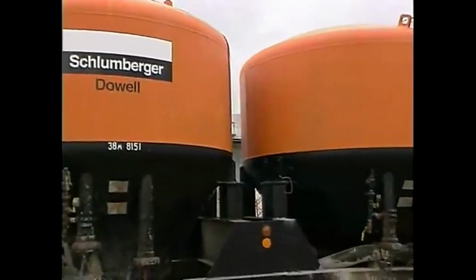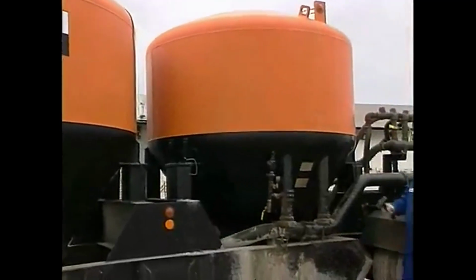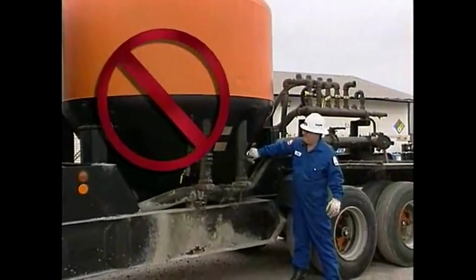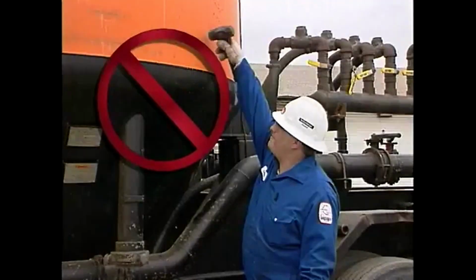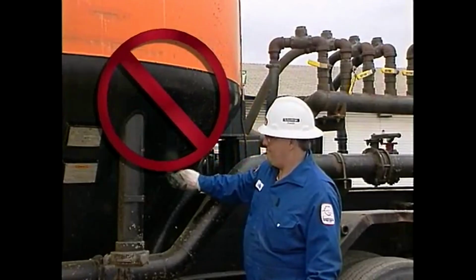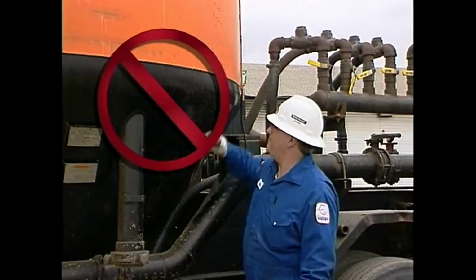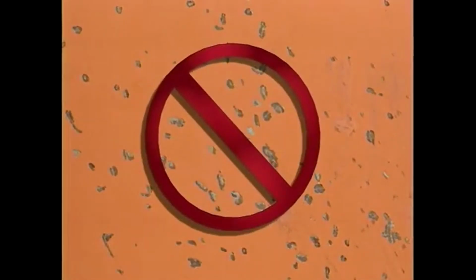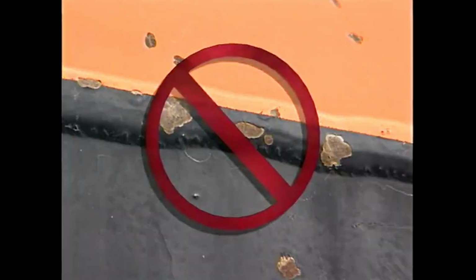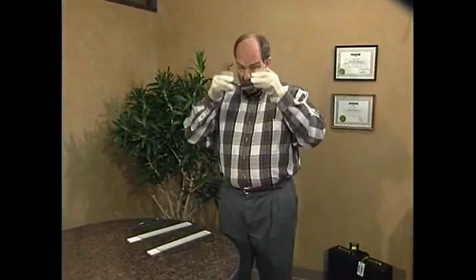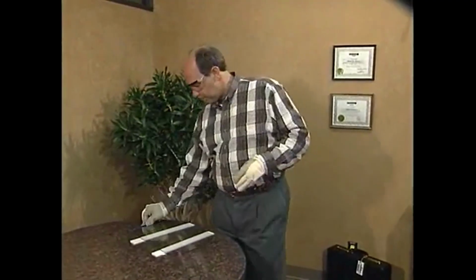For example, thousands of people have hit thousands of pressurized silos hundreds of thousands of times and nothing has happened, at least not at that moment. Hammering on a silo chips off the protective paint. This allows spot corrosion to begin on the exposed metal shell. This spot corrosion can cause small pits in the metal, reducing the strength of the steel. Hammering on a silo can cause an imperfection in the steel that's already under stress from pressure.